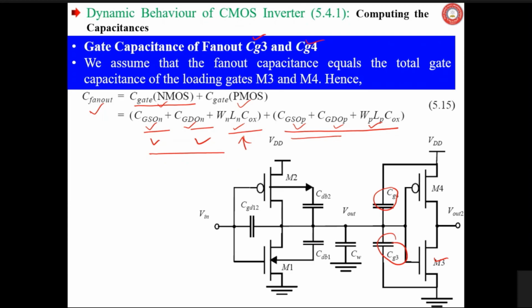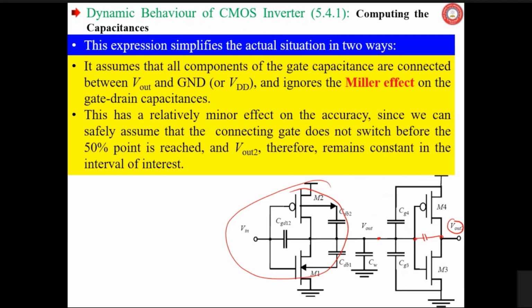another component of load capacitance. Now another thing which is very important is the Miller effect. If you consider this capacitance, then twice of this value has to be connected here with the ground, twice of this CG. That I have already discussed, twice of this value because of the Miller effect.